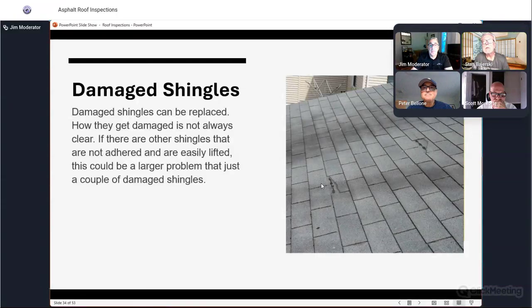Damaged shingles. Are these shingles lifting and then being blown off? If you look at the one that you just circled, Jim, right next to it is cracked. So that day there were only 2. I come back 6 months, there could be 4. I went through that roof as best I could, and there wasn't any that I saw or walked up to and tried to lift that were lifting. But these are the kind of things that are probably not going to leak, right? Because the shingles overlap and there might be felt paper underneath it, but it's got to be pointed out, and you want to protect yourself, so you have to have some kind of blurb about more possibly happening.